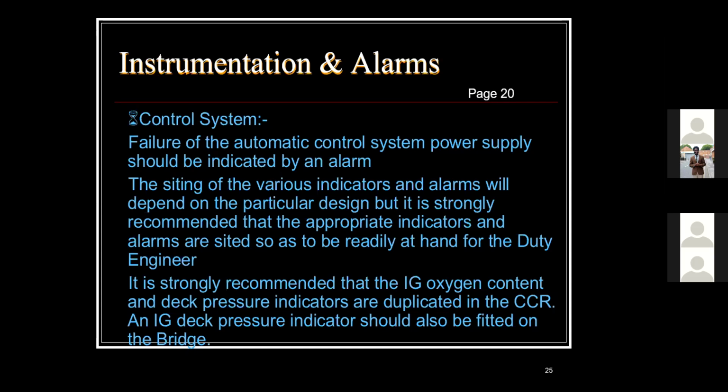You can generate electrostatic charge, and when the oxygen content is not low, it can lead to explosion, because now you have the fuel, you have the source of ignition, and you have the oxygen. What is remaining now is just the disaster. So it's very, very important. Like I said here, it is recommended. It's not mandatory.